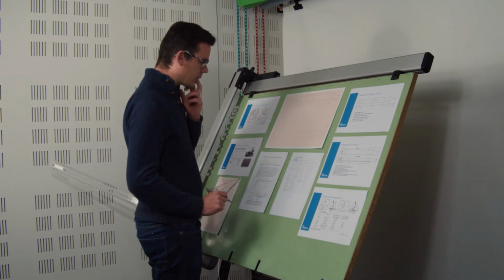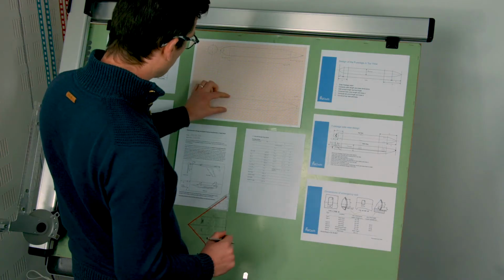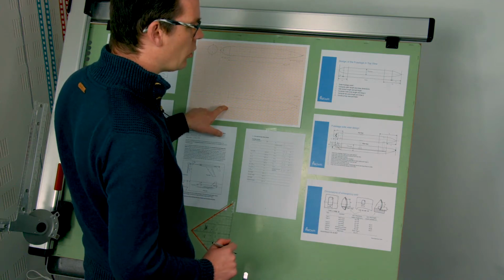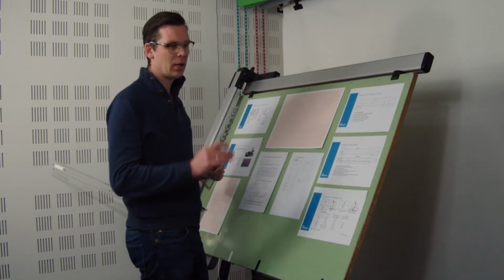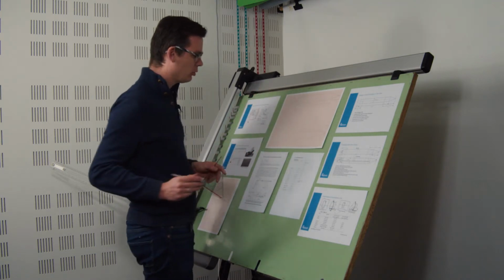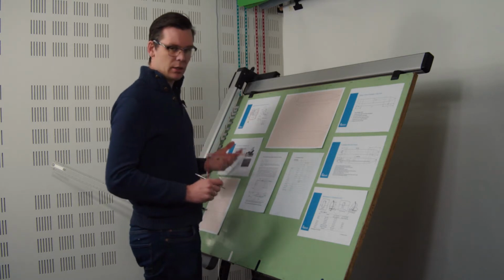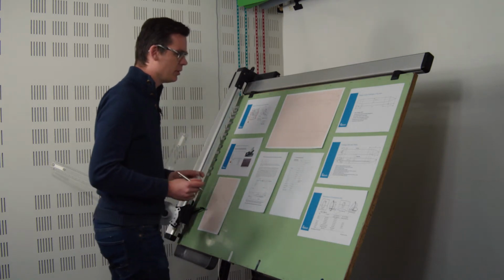The next part is maybe a little bit more complicated. That's the drawing of the nose shape. So before I do that, I actually want to know where the pilot is going to be, because the pilot's eye, the position of the pilot's eye, is important for designing the windshield and therefore that whole cockpit part. Right, so where the pilot eye resides is also part of the design process. To make it a little bit simple, I assume at this stage that the pilot is going to be sitting at the same level as the passengers in the passenger cabin.